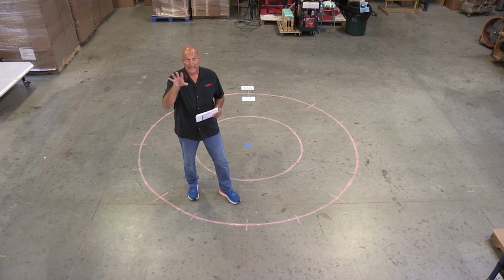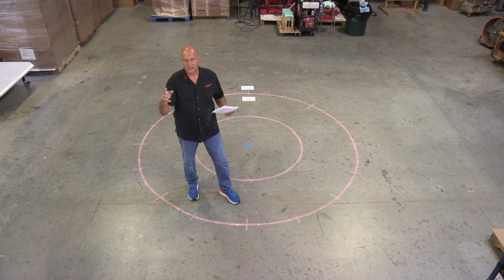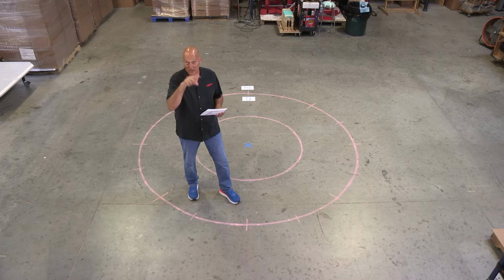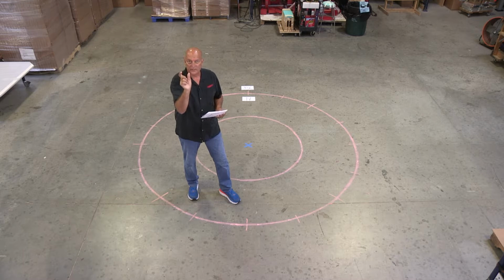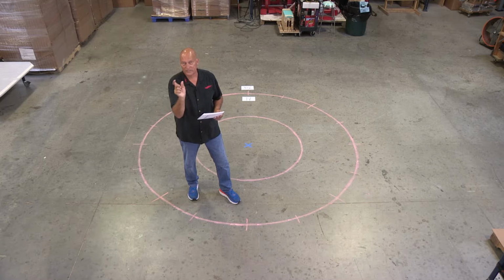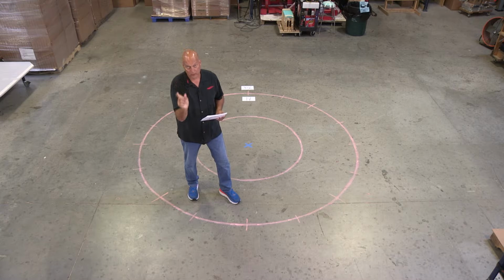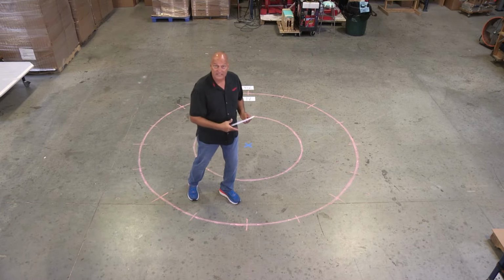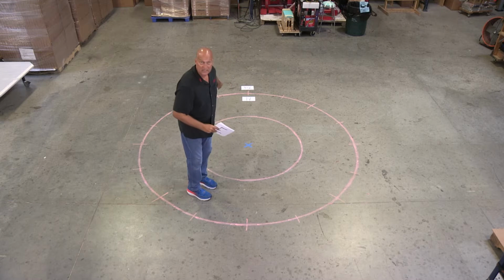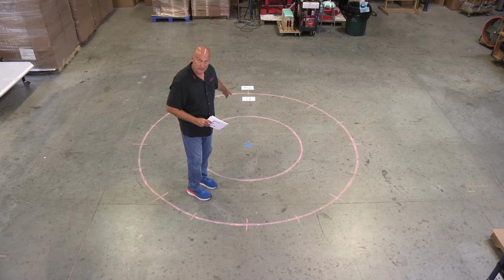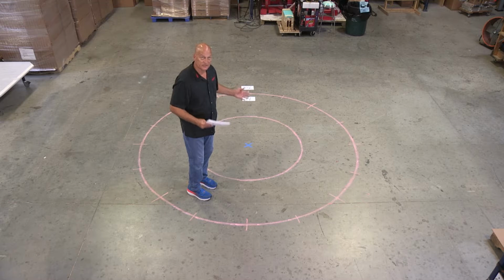When you're looking at a heading indicator, let's say a G1000, on top of your HSI, you've got a little box. That's where you're going to see that heading, correct? And then inside of that, you'll see the letter representation of the direction, right? So I like to lay it out in the same way that students are going to see it on the simulators when they can get back to the simulators.